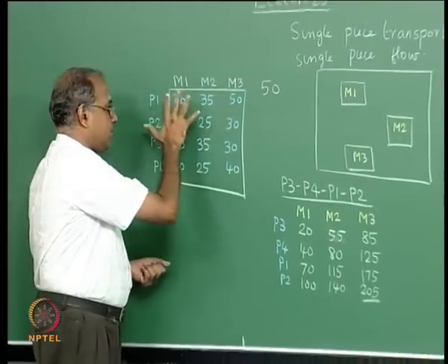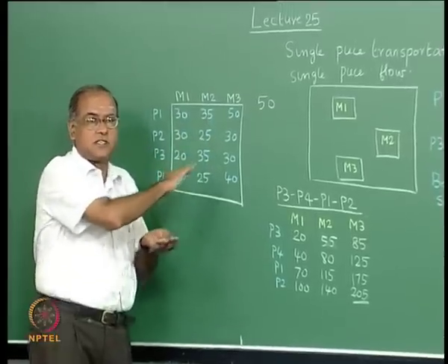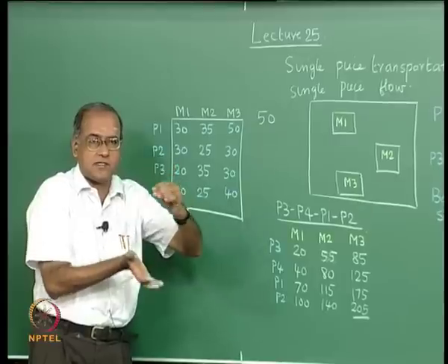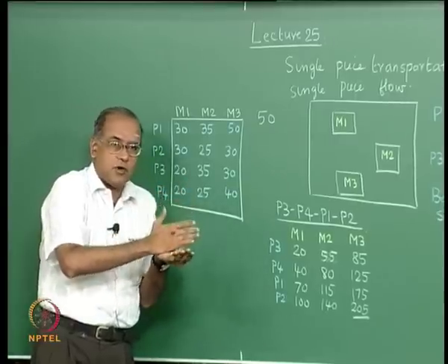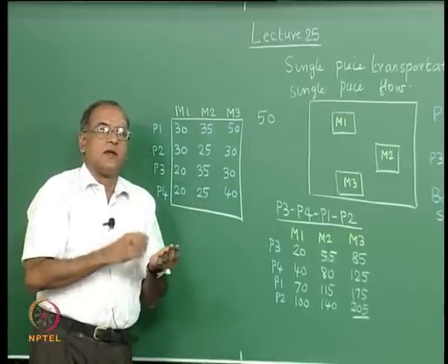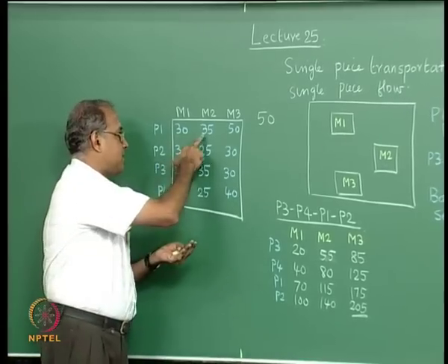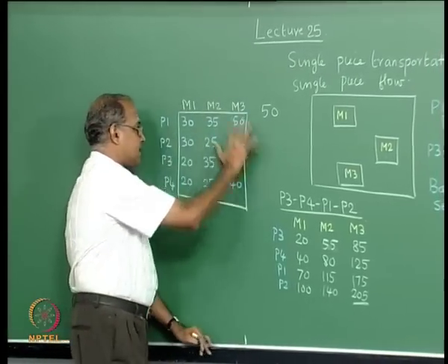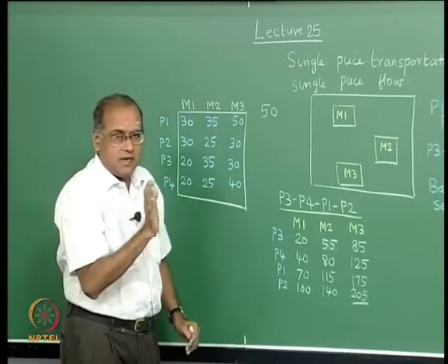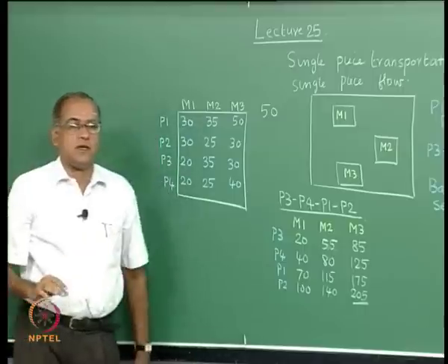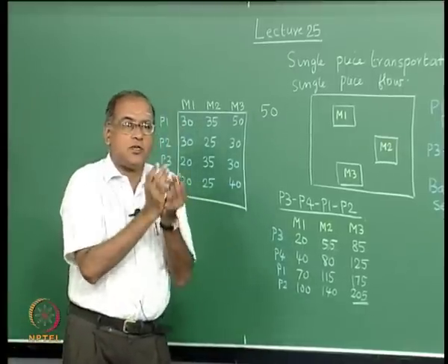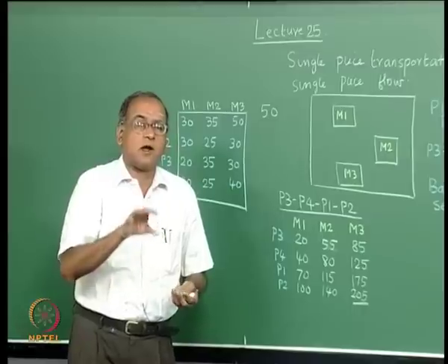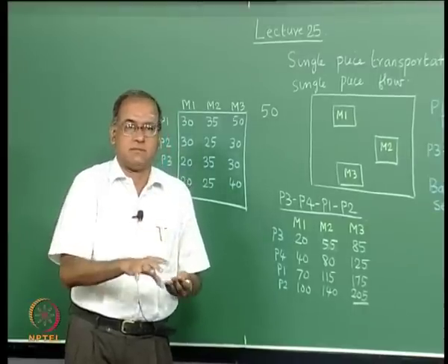Now, here we assumed that the entire transportation is a batch transportation. We wait for all the 10 pieces to be done and then we transport as a batch, and we also have added setup times into the processing times. Normally, the total processing time that is given in any flow shop kind of a problem is the setup time plus unit processing time into the batch size. Now, this batch size is called production batch size, which is 10.